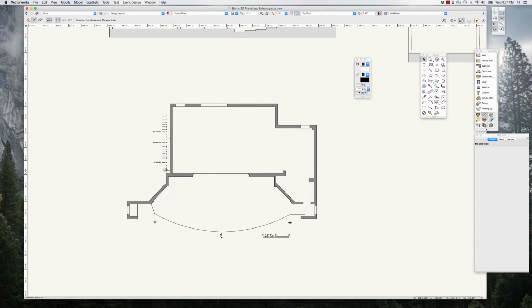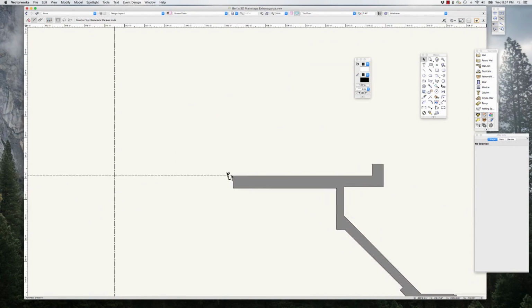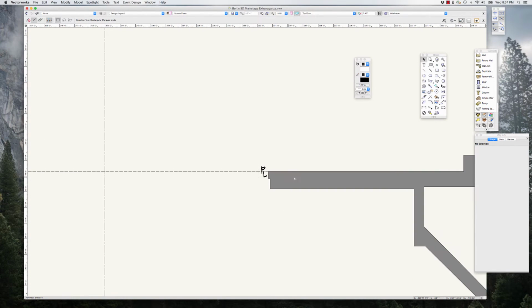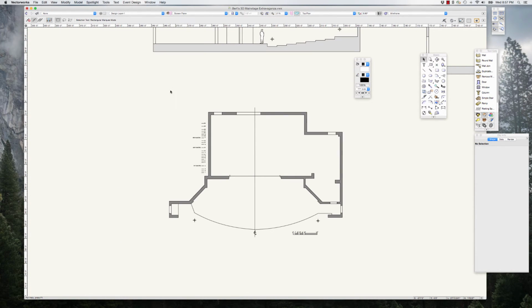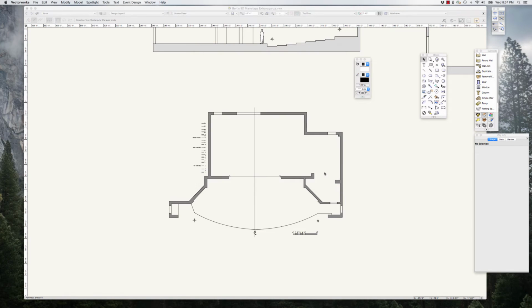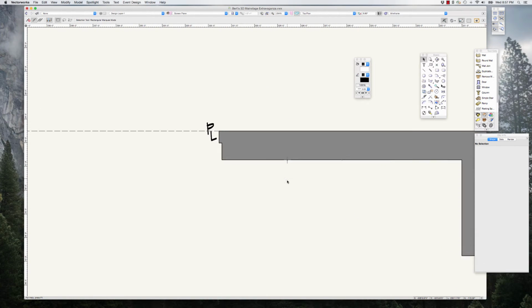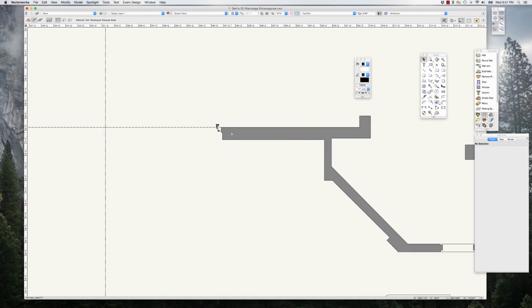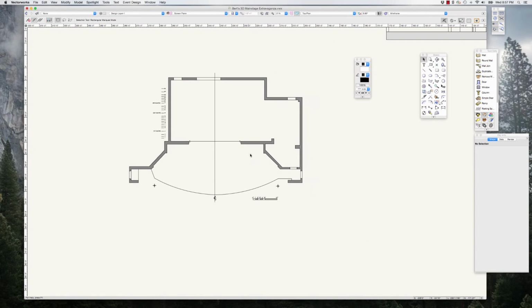And then everything else, let's just set everything to 0.25 and then go back and change our imaginary lines to 0.13. It looks like I don't have zoom line thicknesses on, if you remember that from last semester. Let's see, display, no, zoom. So yeah, these are thicker than that, so that now it looks like it's supposed to.